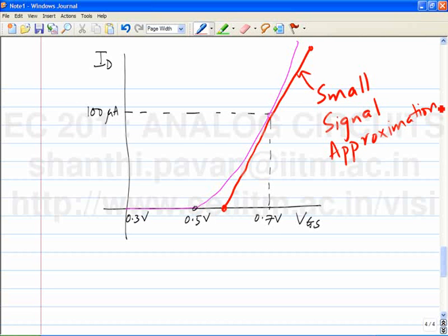Alright? And what have we done to compute the swing limit? The voltage Vs required for the transistor to go into cutoff. Which point on this diagram represents that? What have we done? In other words, the equation of this line is ID plus GM times Vs. That's what this straight line represents.